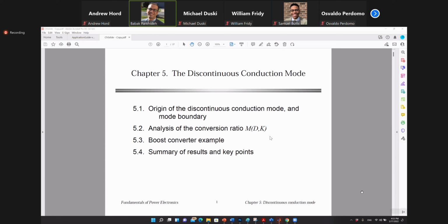This switching loss that is dependent on the switching frequency matters, because in one case conduction losses are higher, but the switching loss per switching frequency is lower. So there is a midpoint where either of these solutions may give you a better efficiency, and the switching frequency determines that. So let's say the final answer for you would be like below 50 kilohertz, Option A is more efficient than option B. Right.